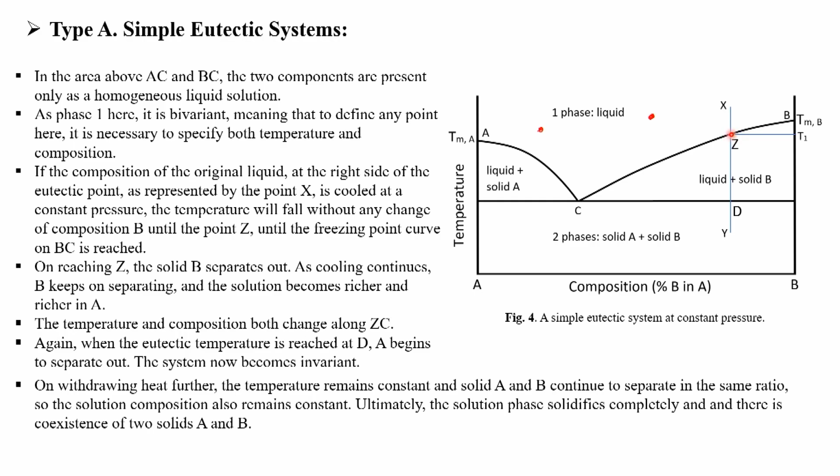So if we further cool down here, solid B separates out, and then the solution becomes richer, so we get more and more A here. The temperature and the composition both change along ZC. Along ZC, temperature and composition both change.